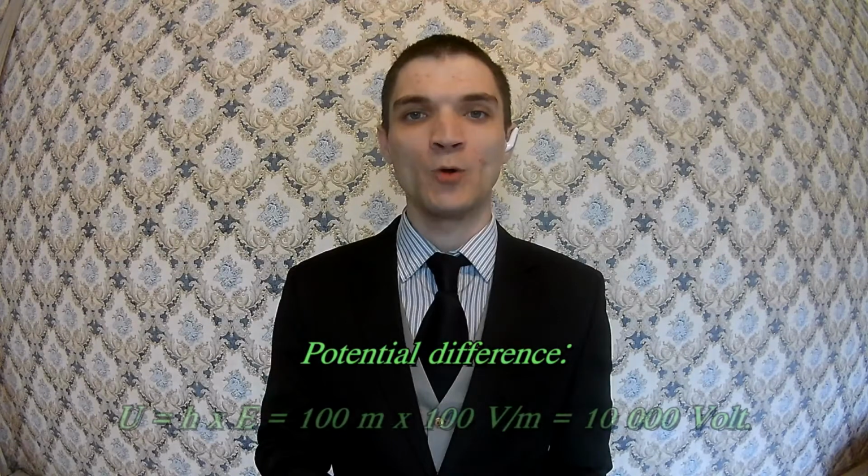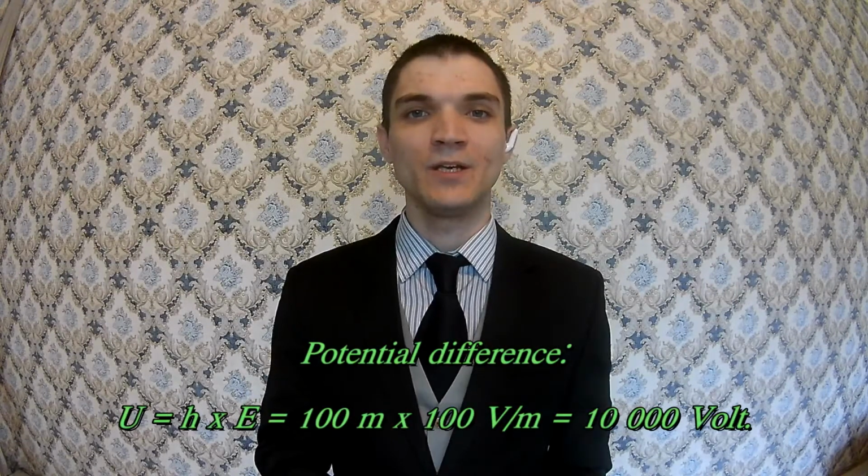Let us estimate the capacity of such an installation. Let the top point of the conductor be at a height of 100 meters. The average electric field strength over the height of the conductor is 100 volts per meter. Then the potential difference of the electric field between the Earth and the upper point of the conductor will be numerically equal to 10,000 volts.